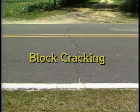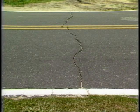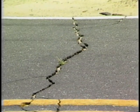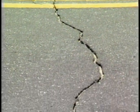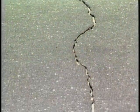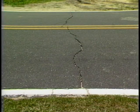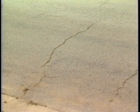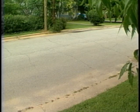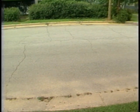Block cracking, also called shrinkage cracking, is a distress which often warrants crack sealing. Daily temperature changes cause expansion and contraction in the pavement. As the pavement ages and hardens, it is less able to withstand this stress. It pulls apart, creating block cracks. Block cracking most commonly occurs on plant mix pavements. Block cracking begins as transverse cracks. These transverse cracks eventually become connected with longitudinal cracks, forming blocks, hence the name block cracking.